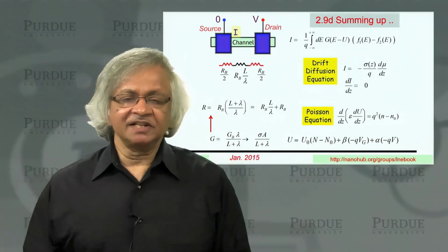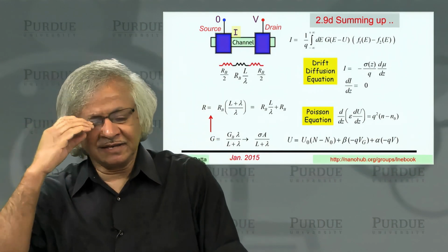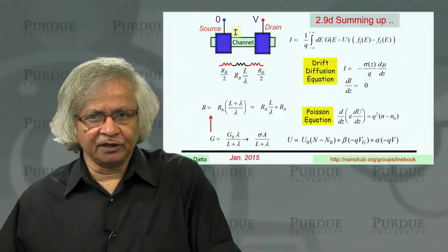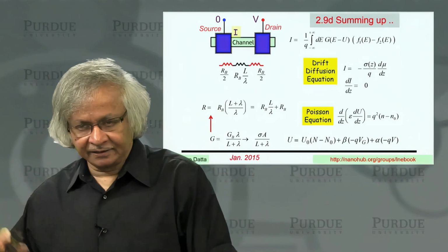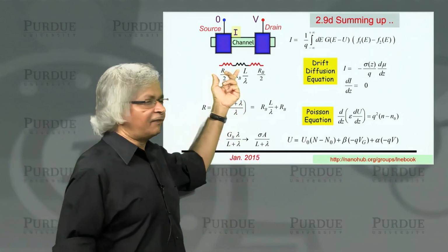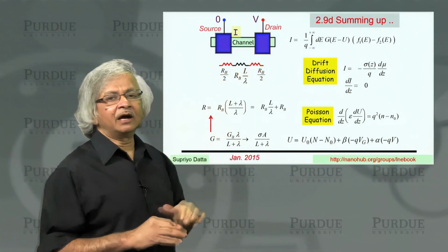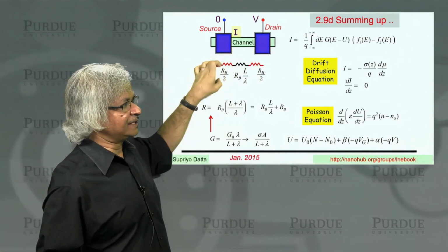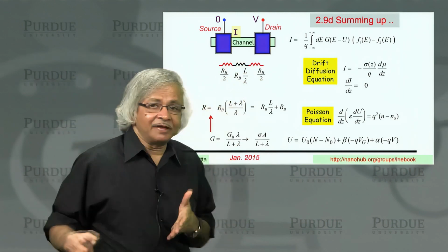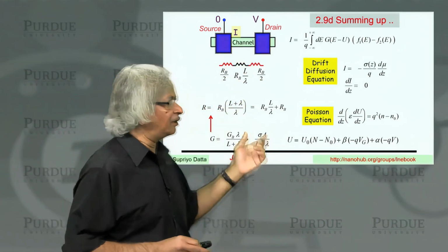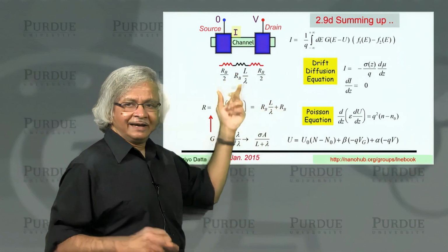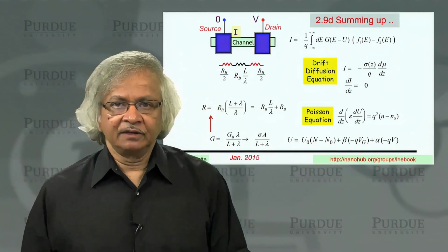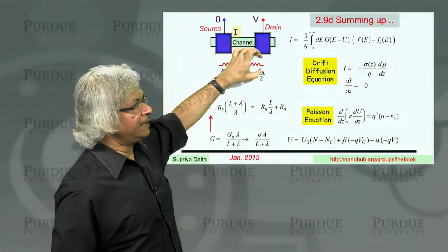That's well known. But usually you think of this contact resistance as kind of an undesired thing, which you can always get rid of with enough engineering. What is not recognized is that there is actually a fundamental limit: no matter how good your contacting technology is, finally you will always have this ballistic resistance appearing at the interfaces. Now this is something we haven't talked about so far. We didn't quite talk about where this RB comes from. And that's what we do in the next unit of this course. That's what we'll get into, as to why this appears at the interfaces.